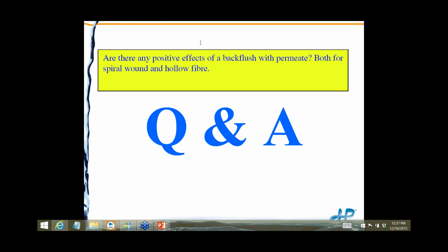Because of the membrane's construction, it is not advisable to ever go from permeate to feed with pressure. So you're pressurizing the permeate side and forcing water molecules through. The way the envelopes or leaves inside the membrane element are constructed, they're built for water to go from the outside to the inside of the leaves, not the other way around.